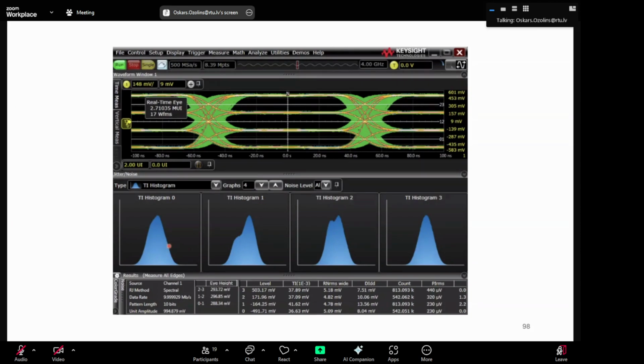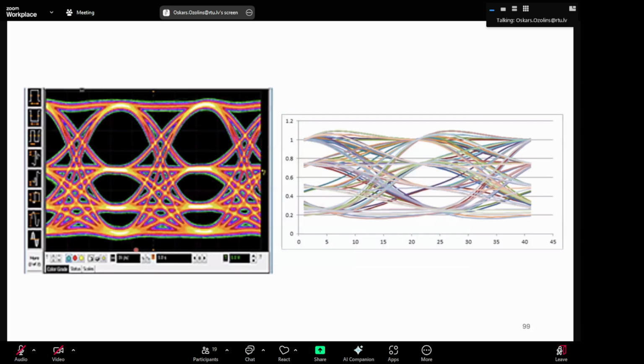That's one more point when you look at these estimations of signal performance: you need to know that the statistics for each level are close to Gaussian. I'm going to talk today a little bit more about bit rate estimation from eye diagrams, and there you need to be aware that if the distribution is non-Gaussian, then maybe you don't have a good estimation of bit rate. So this is just another example of these kinds of impairments.